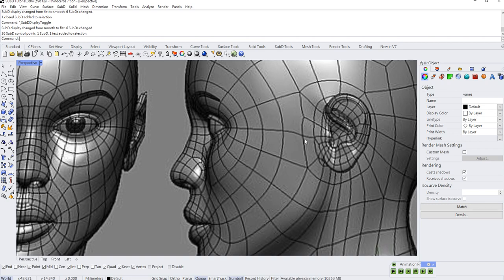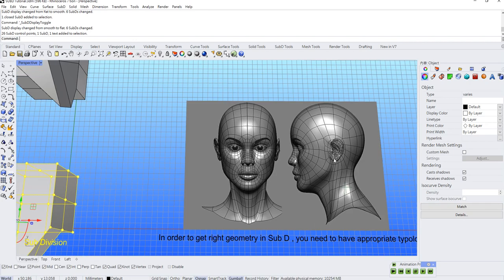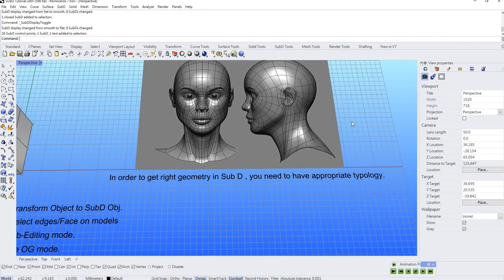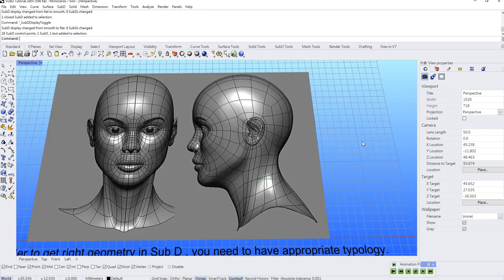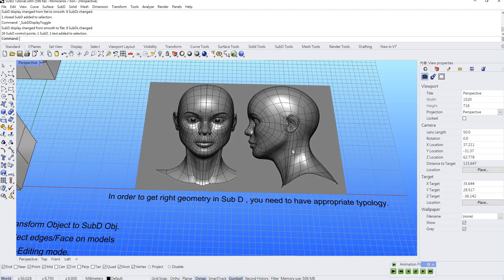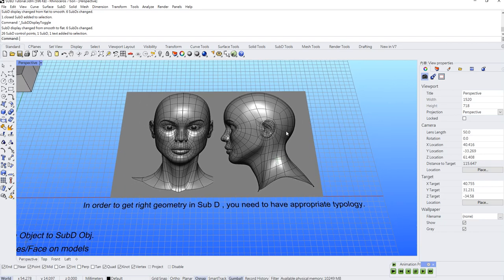But anyway, when you are going to do modeling, try to avoid the face which has more than 5 edges. And also, only in certain circumstances we will use triangle faces, because triangle faces are also not that good. And if you want to use triangle faces, you need to be pretty sure about the flow of the faces, but that's something more advanced, and probably until next semester I will tell you how to do the appropriate topology when you are working on a character model. Anyway, just giving you a preview.